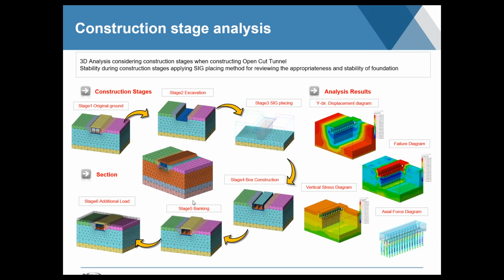The premise being that once you're working on a more advanced project, you really do want to make sure that at every one of the stages you're able to accurately reflect what's happening in terms of stresses on the ground, the potential failures of the ground, how the support systems are in place, what the sequence should be, how far you should excavate, how much reinforcement or support system needs to be in place.